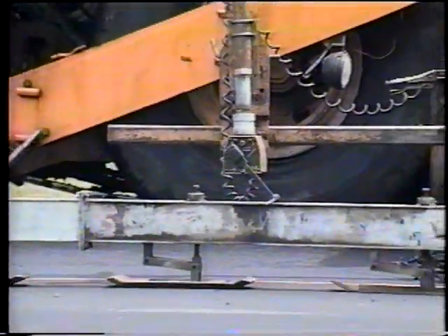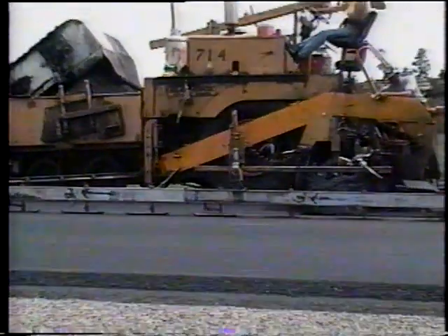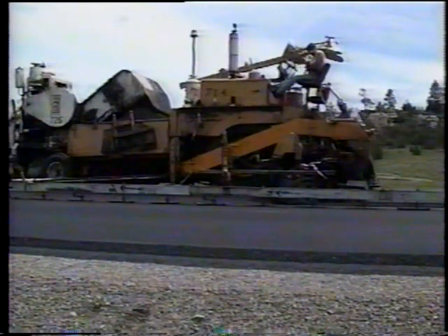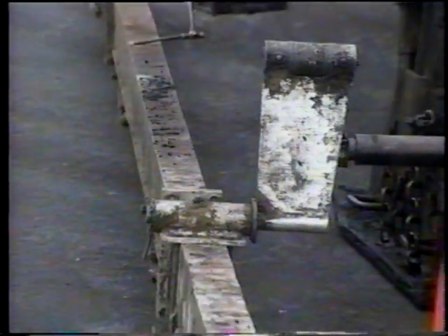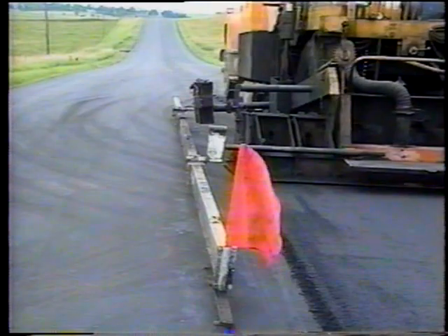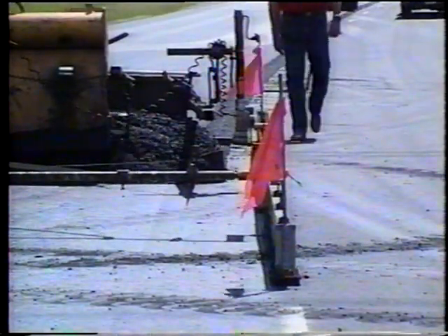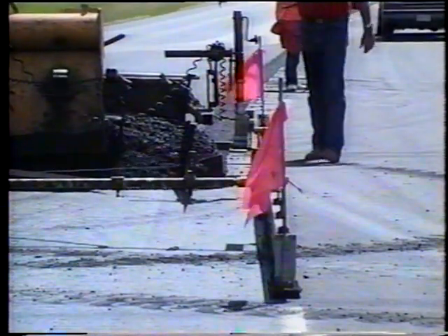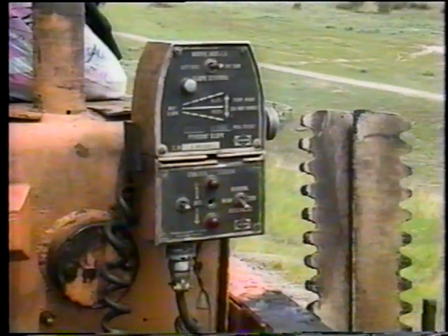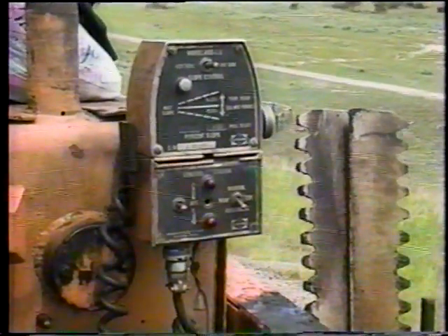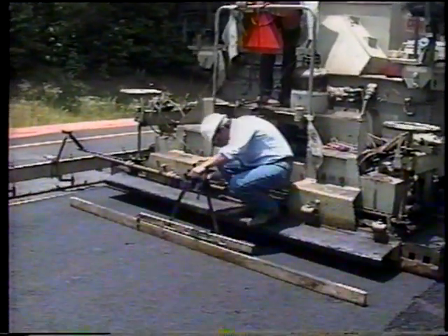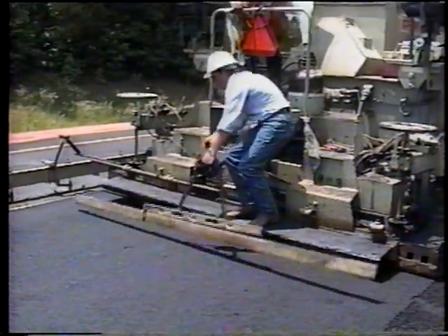Now let's look at grade and cross slope control. You'll remember from part 1 that the pavement grade is controlled by a sensing device with a long ski. You should watch the ski as the paver moves along. Make sure it pulls straight while remaining parallel to the longitudinal joint. If these conditions are met, the rest is automatic, for grade control anyway. As for cross slope control, see that it's properly set and that the contractor checks it from time to time with a slope board. Be on the lookout for excessive cross slope. That's just a waste of material.